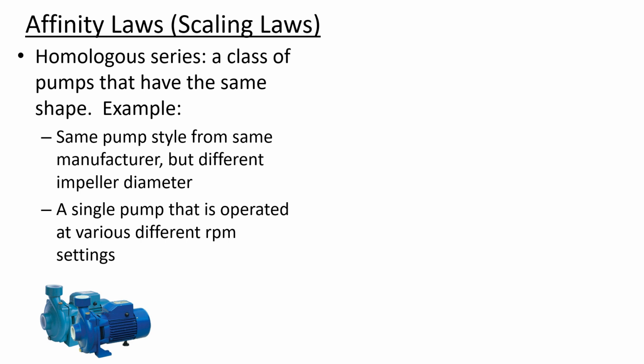And so if you plug in a pump, it's going to be expecting that 60 hertz electricity and the alternating current, but a variable frequency drive can adjust the frequency of that cycling, and it's a way to slow down pumps so that they operate at a different speed than their original speed. You could decrease the rotational rate of the pump by changing how frequently the electricity is cycling between positive and negative. If you had a VFD, then you wouldn't necessarily know how the pump is going to behave at a different rotational rate.